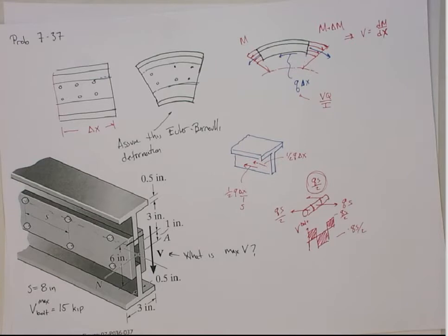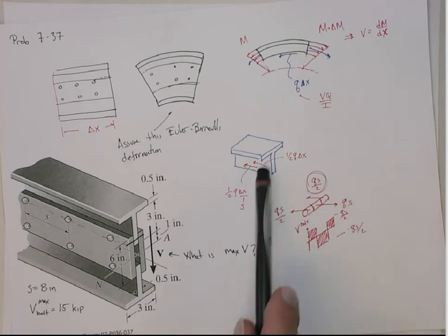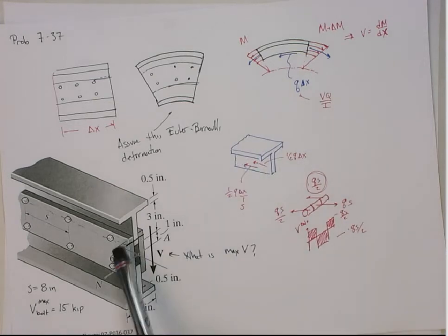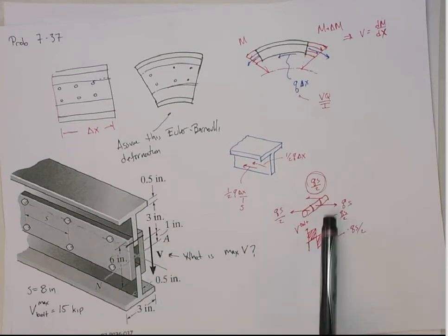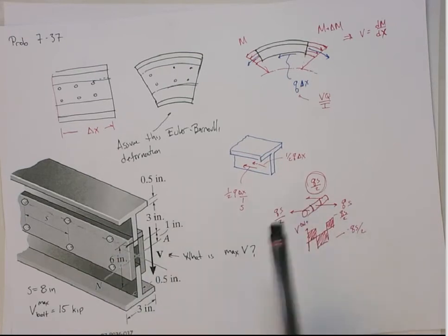All right, so now that we got that, that's kind of the conceptually difficult part. Once you buy into that, and you realize that, okay, it actually is that transverse shear stress, the VQ on I, that this bolt has to pick up. It picks it up in double shear, right? So that the shear is actually half of that, right? So it's half of the QS on 2.